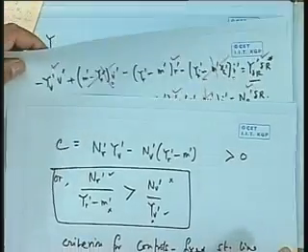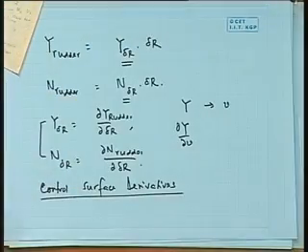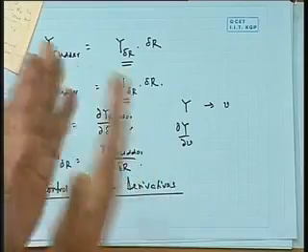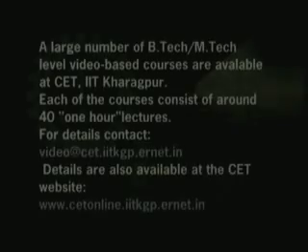In other words, only for a stable ship, I'll do that afterwards, only for a stable ship, you will find that if you give a rudder this side, the ship turns that side. In other words, you are actually assuming there is a stability involved somewhere. Anyhow, that we will discuss in the subsequent class with respect to our definitive maneuvers. But this is where I will stop here. So, what I want to sum up is that there is something called stability criteria, which is an intrinsic property of the hull. So if you have a bad hull design which has an intrinsically unstable hull, then obviously you will need much more rudder control to make